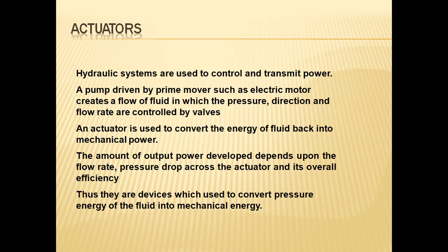Hence these are the devices used to convert the pressure energy of the fluid, pressure energy which is created with the help of the prime mover, that is the motor, into mechanical action. That is nothing but the movement of these actuators, either in linear or rotary movements, and vice versa, both in clockwise and counterclockwise directions.